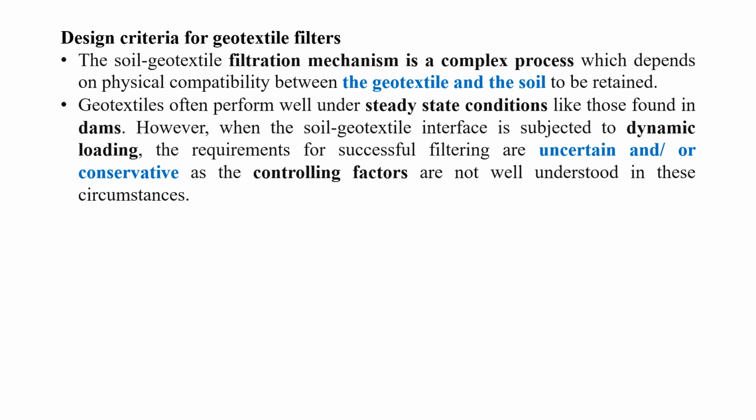Geotextiles often perform well under a steady state condition like those found in dams. However, when the soil geotextile interface is subjected to dynamic loading, the requirements for successful filtering are uncertain and conservative, as the controlling factors are not well understood in these circumstances.